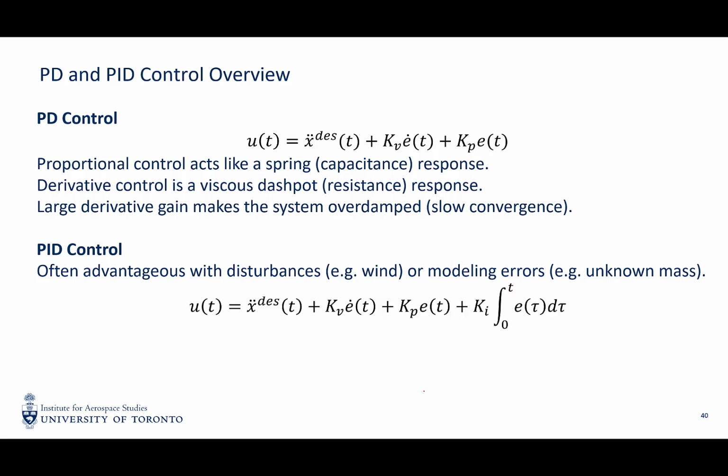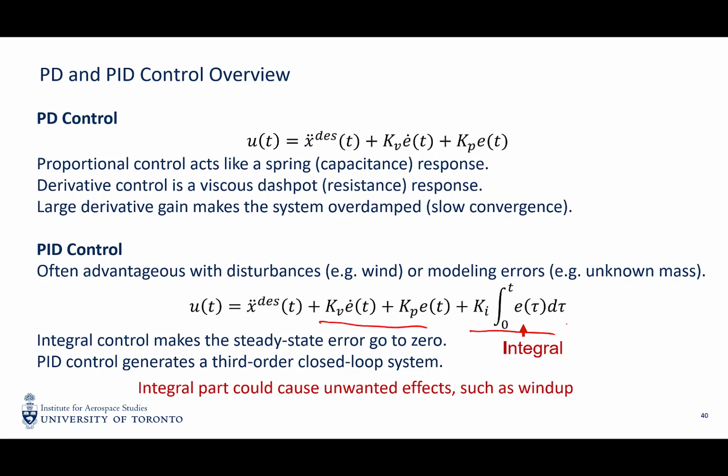In this case, the PD term is not enough for achieving zero steady state error, and we need to integrate the error with respect to time to add additional compensation for the persistent disturbances. However, if you set too high of a Ki term, the integral term, it will add instability to your system, such as windup. It's like a saturation in your control input.